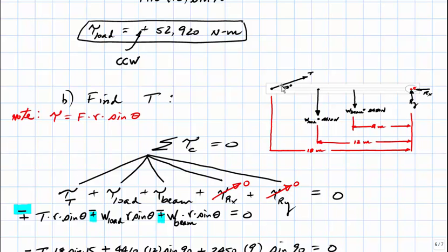And the answer has to do with this angle. This is a very small angle. It's a 15-degree angle, which means that the Y component of the tension is relatively small when compared to the overall tension. And of course, it's the Y component of the tension that counteracts the weight of the load and the weight of the beam. Therefore, we need a very large tension in order to get a relatively small Y component to counteract these two loads. Let's evaluate part C of the problem.